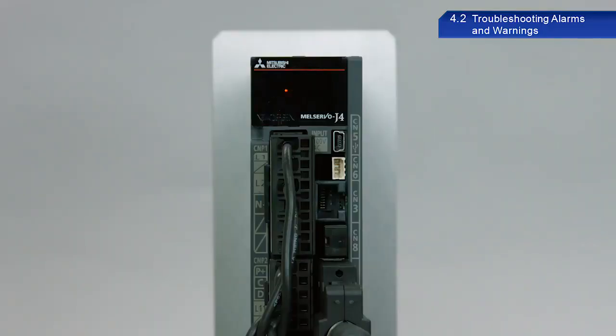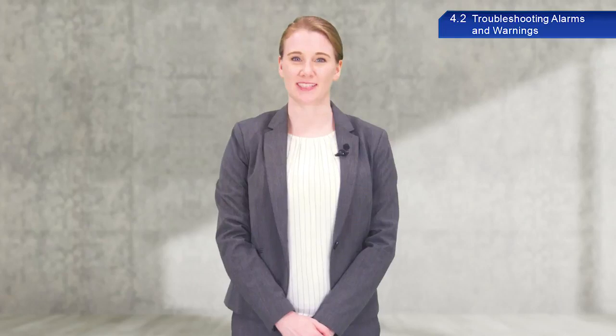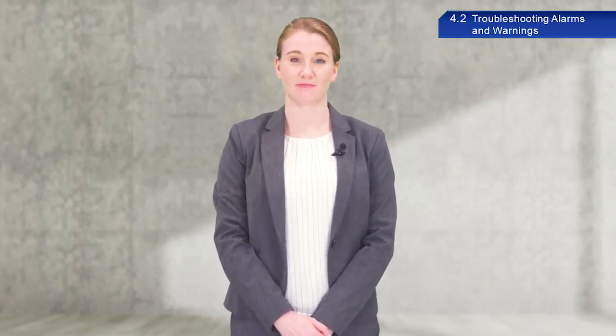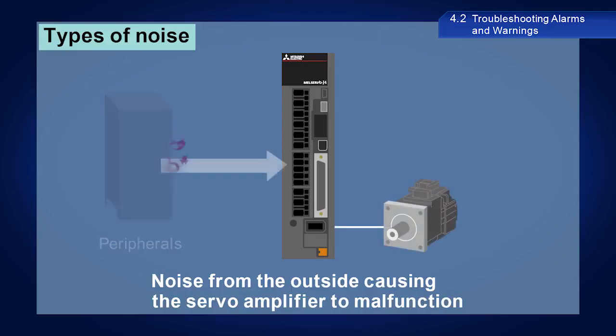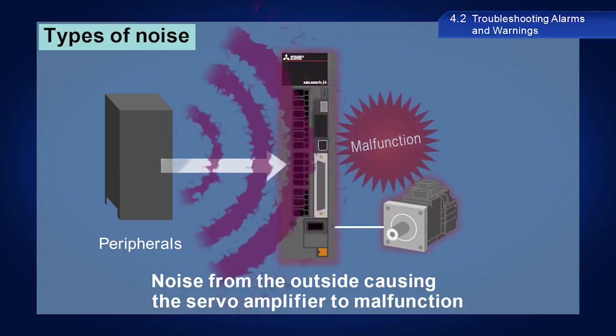The alarm with an alarm code of 20.1 is the encoder normal communication receive data error 1 alarm. This alarm is caused by environmental factors such as noise. Noise can affect various electronic devices and can be generated from a wide range of sources. The intrusion of external noise can cause incorrect servo amplifier operation.